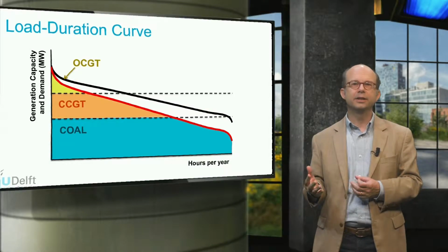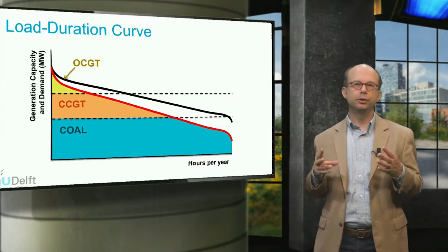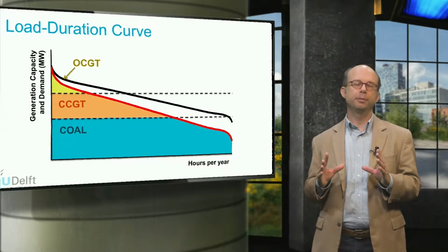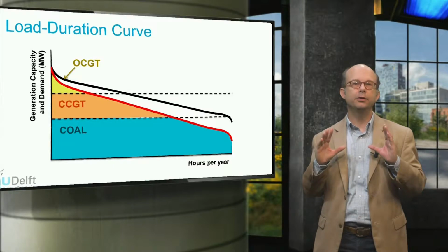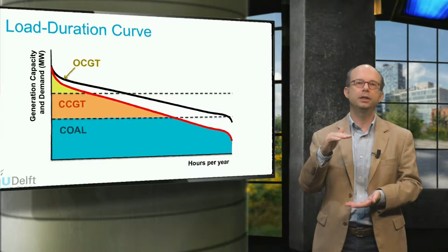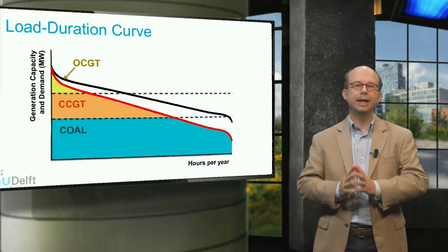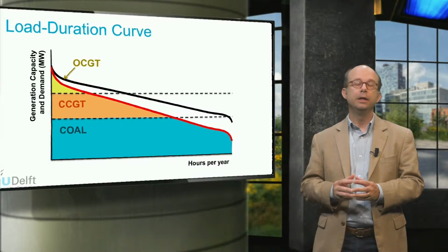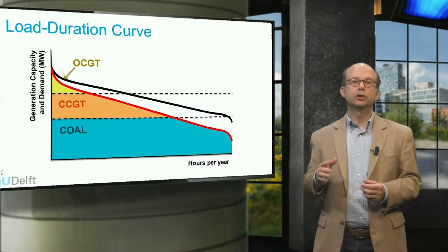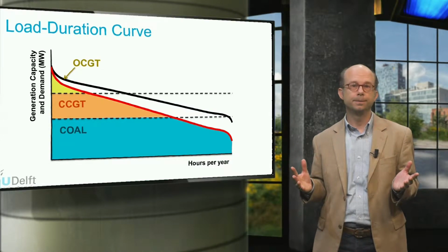So what is the effect of solar and wind power on the power system? They reduce the volume of energy that needs to be provided by conventional power, but they may not reduce the volume of installed capacity that is needed to meet the peak demand in the year by much. Please note that this latter effect depends on the location. In warm, sunny locations, solar power will contribute more to peak demand than where I live in the Netherlands.